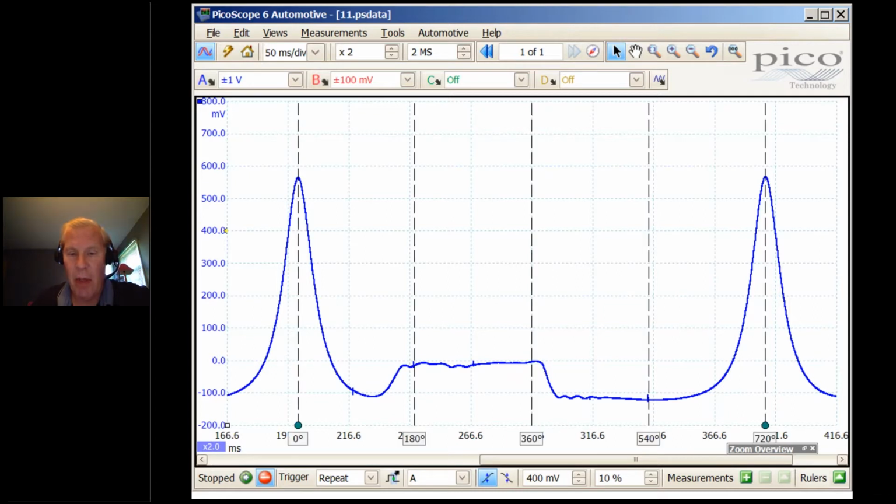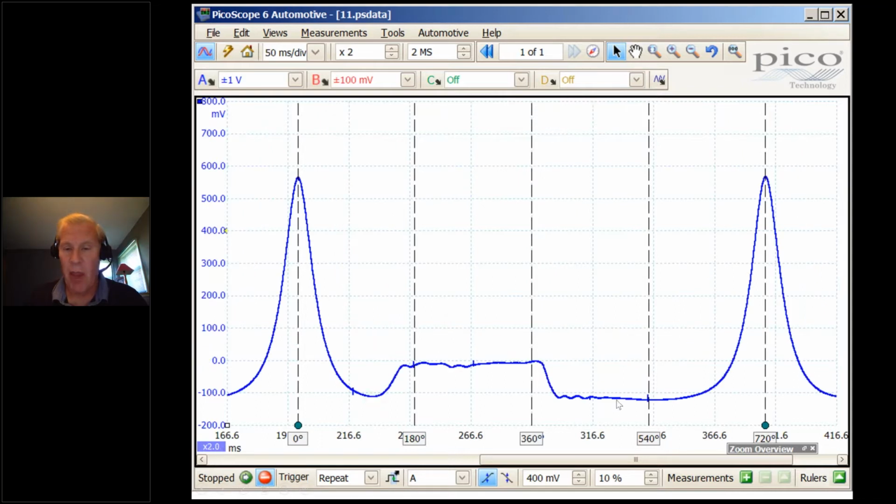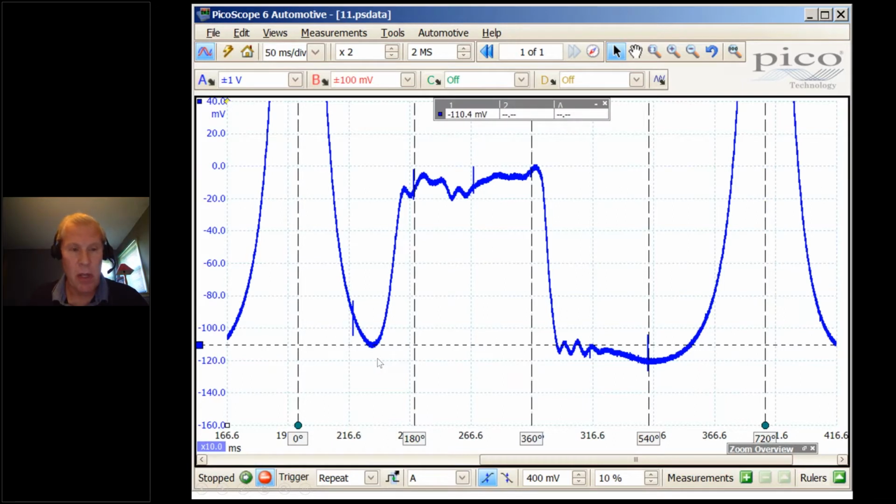Divide this up. I'm going to zoom in a little bit. Look at the depth of the expansion stroke vacuum and the intake. Please notice they start out good. That depth, about 22 inches, then something happens. Something happens that pulls it even deeper. So we started out okay, then something happened, and we pulled even deeper before we go back and start to move upward on our compression stroke.